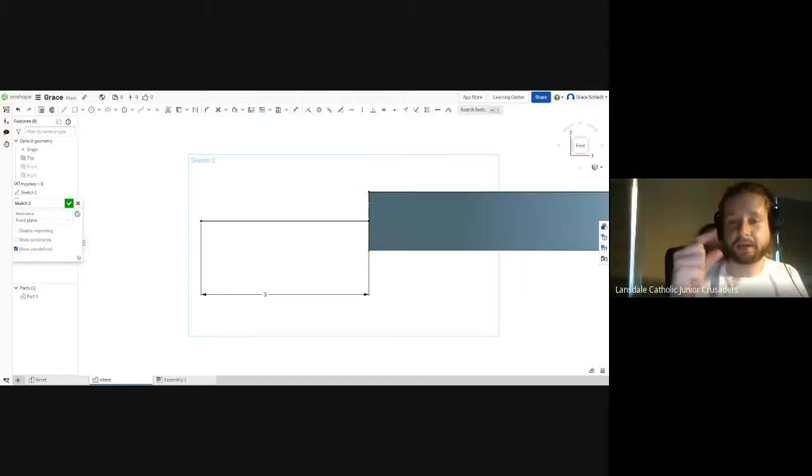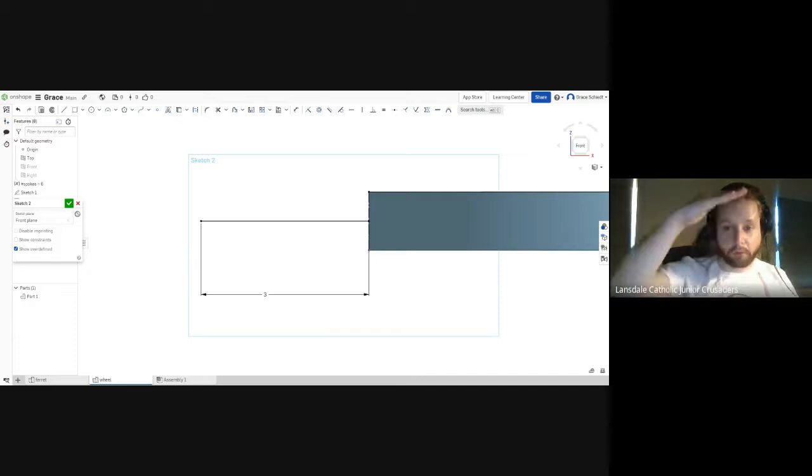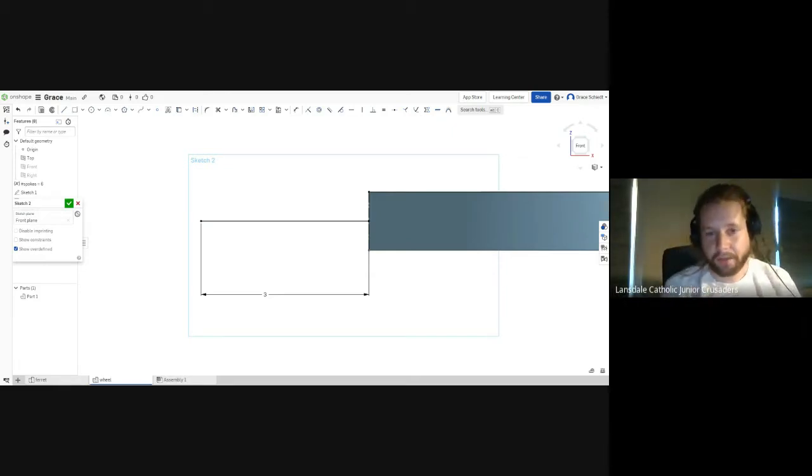If you put a dimension there for the height, every time you change the thickness of your ring, it wouldn't be centered. You'd have to re-go and re-edit that value. But because you constrained it in such a way, it will now always be centered on the ring. Make sense? Yeah. All right, cool. Now you're going to draw the profile. Like if you were to cross your guy and cut your post in half, your peg, draw that profile or half of it and see what you can come up with. It could be interesting. It could be a weird shape. We can always edit it later. If you want to make it really simple for now, just do a curve at the end and then just do a line back to the base.